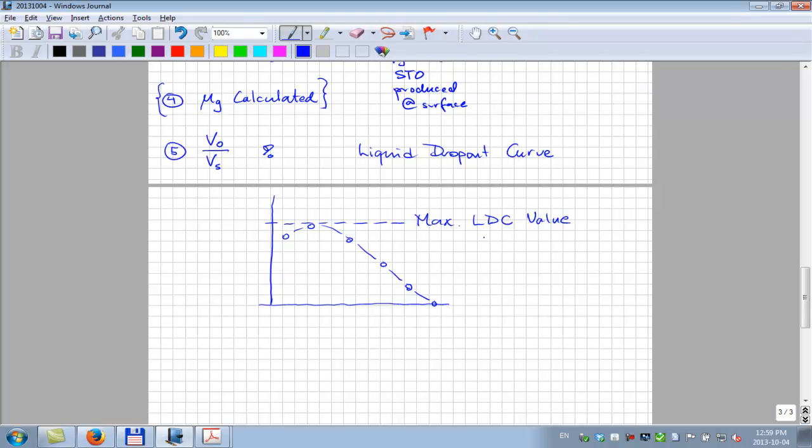So this basically gauges, in a very semi-quantitative way, the richness of the gas condensate. And typically it'll range from 2% for a very lean gas condensate to as much as 40%, maybe plus, for very rich condensates.